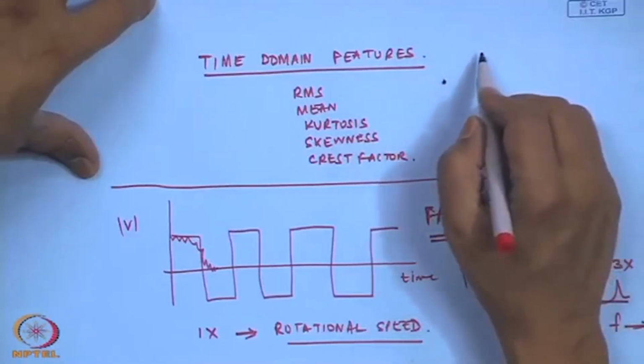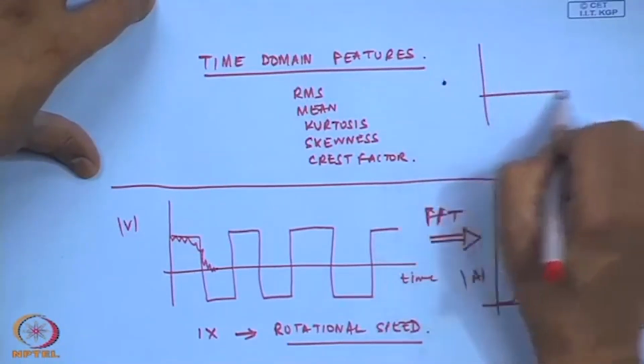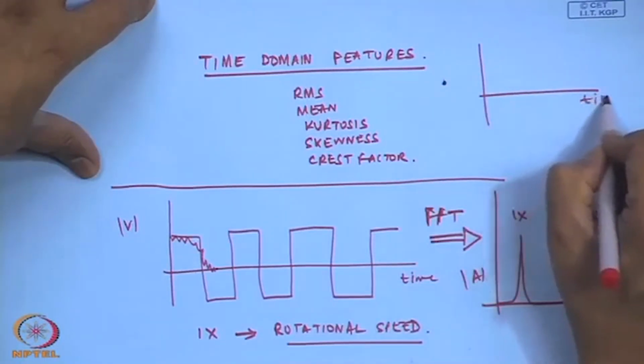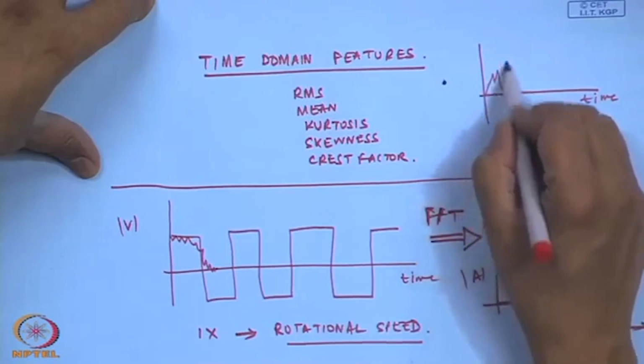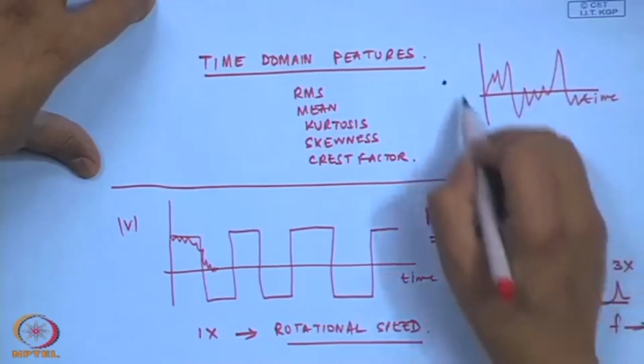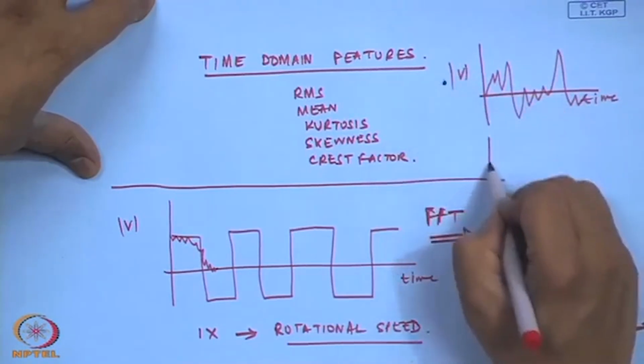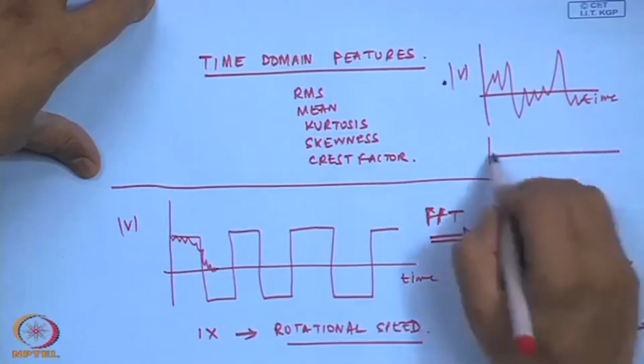However, wherever possible, try to install a rotating speed measuring device like a reluctance probe, an optical tachometer, or a laser based system, so that whenever you are measuring the vibration, you also have the corresponding RPM trace.